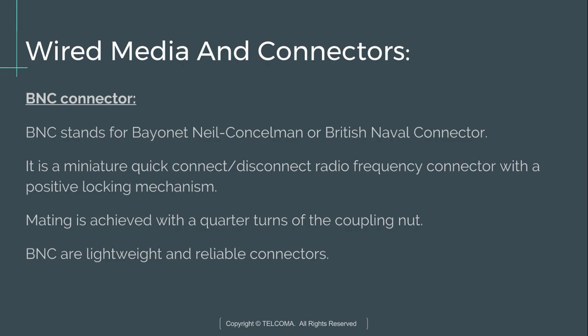Then next is the BNC connector. BNC stands for Bayonet Neill-Concelman, or British Naval Connector. It is a miniature quick connect disconnect radio frequency connector with a positive locking mechanism. Mating is achieved with a quarter turn of the coupling nut. BNC connectors are lightweight and reliable.